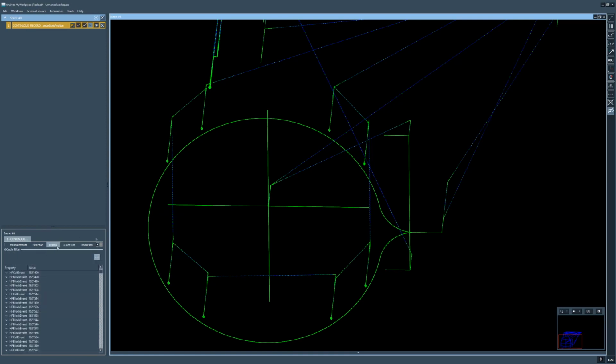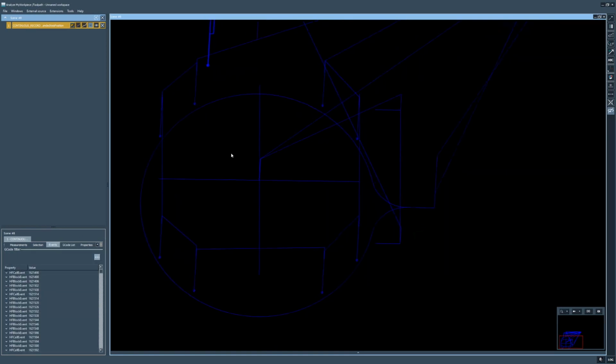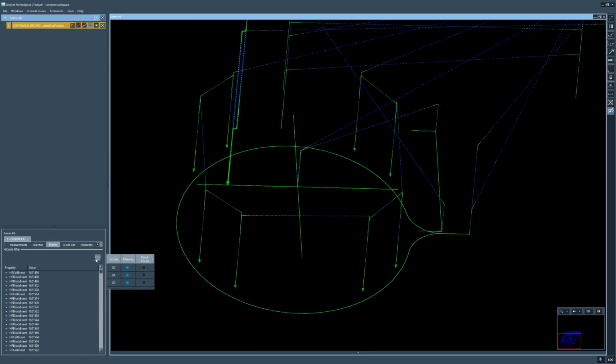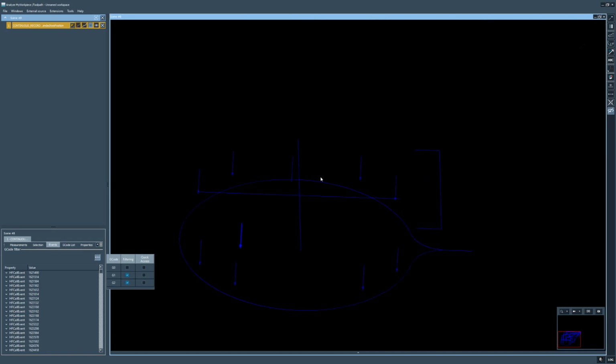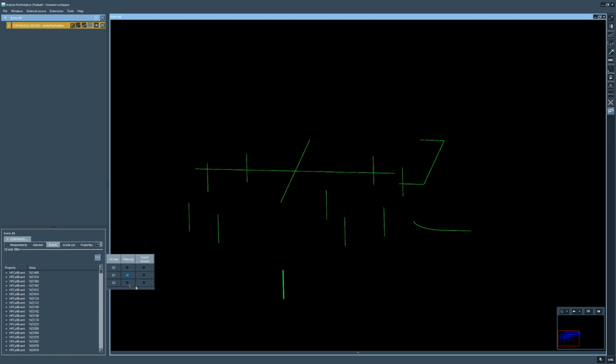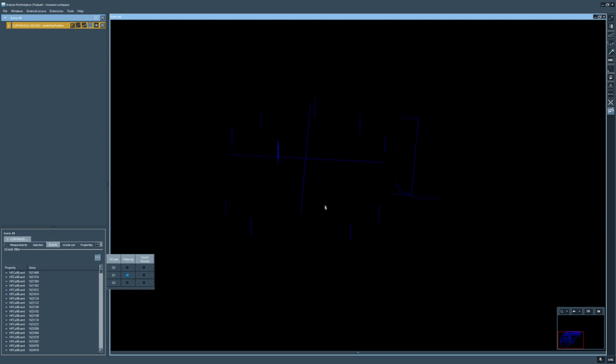But what we now also can do is, when we have data from Capture and Capture for Analysis, we can filter by events. So we can say, okay, please filter out all the G0 events. I only want to see the G1 and G2 codes. This you can do here. If we filter out G2, then we end up with even less.